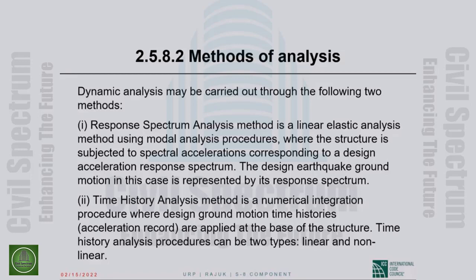However, if you recognize reality and assume that in the process of responding to the ground motion that we have imparted to the base of our structure, selected portions of selected structural members become inelastic and undergo inelastic deformations, then what we are doing is inelastic response history analysis, which is the most sophisticated analysis we can do. And for most important projects today, that is the analysis that forms the basis of design.